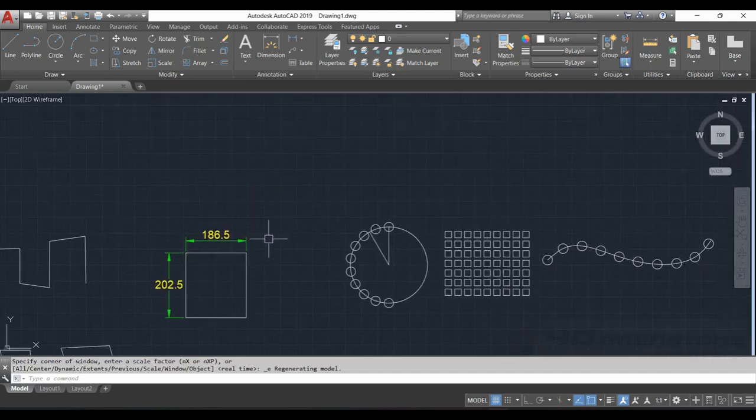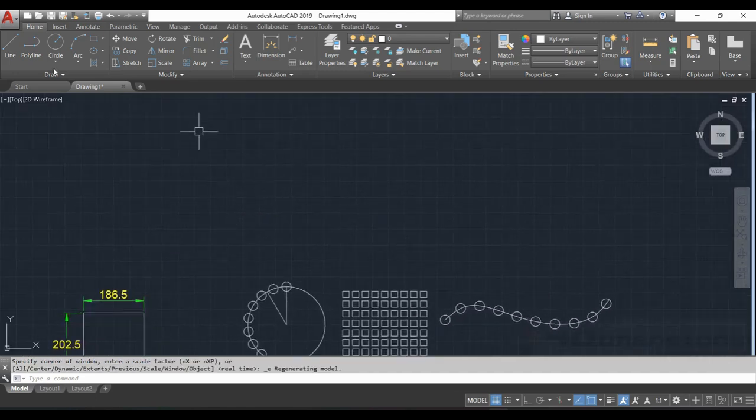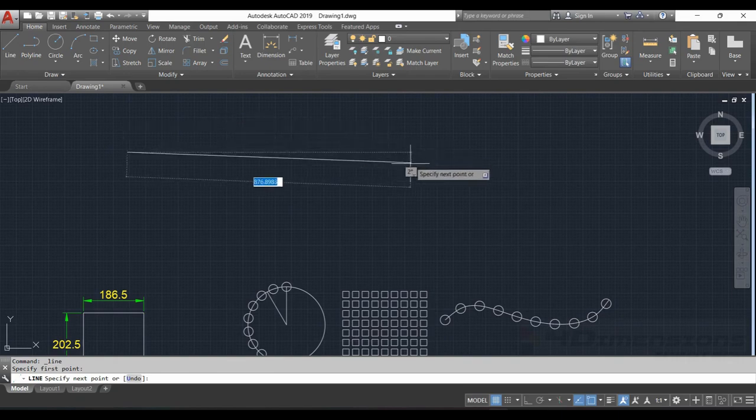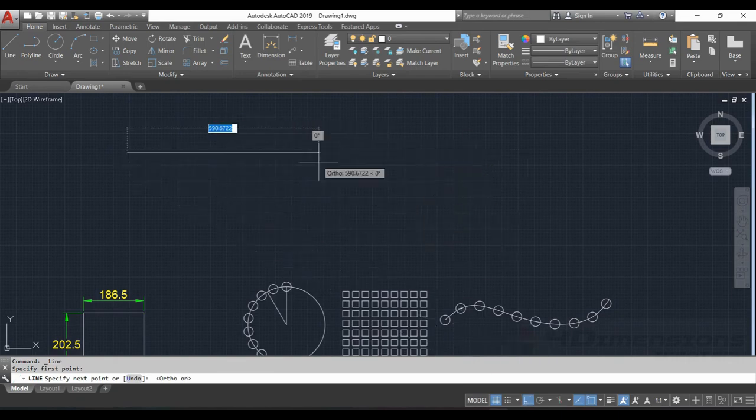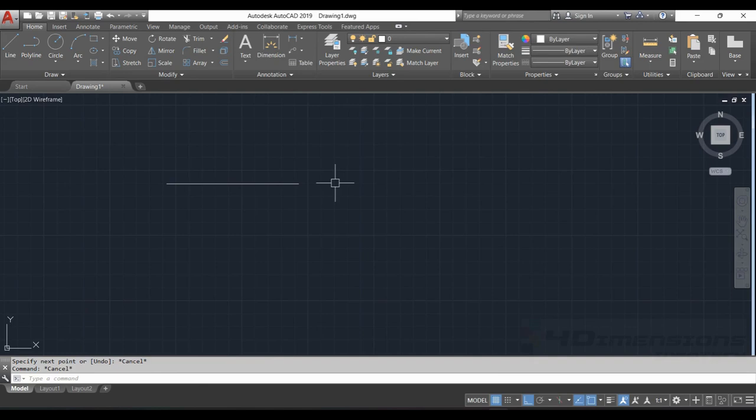The next command we are going to see here is the Lengthen command. This command is used only to change the length of lines. Suppose I am going to keep this line length as 100 mm, and now we'll go for the Lengthen command. Shortcut key LEN, enter. Select the first type as delta. If I want to increase the length, then I need to add the value here. Say delta length as 50 mm. I'm taking this value positive, so it is going to add the distance here.